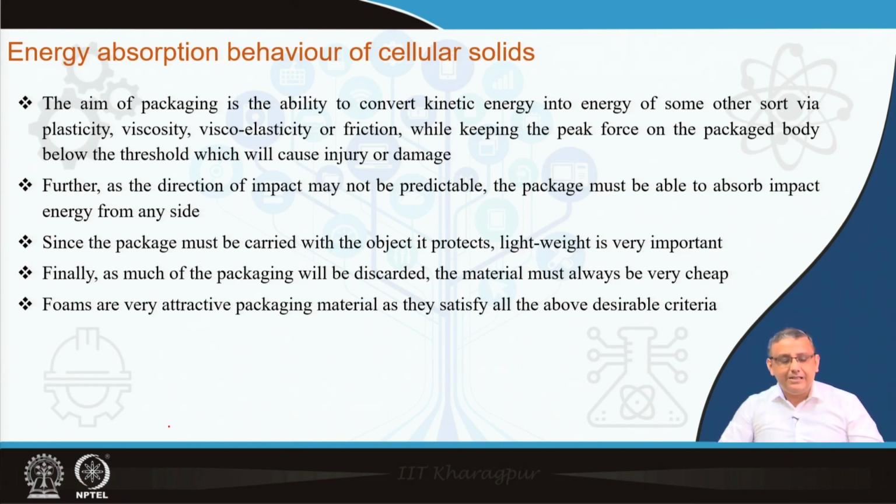Now, because of these things, as we already learned and will also see in the next few slides, the deformation behavior of the foams is very important. We learnt about them in detail in the last few lectures, and we will also go through some details in this lecture. But what are the most important properties for foams if they are to be used for energy absorption applications? One very important point is that the crash can come from any direction, which means the package must be able to absorb the impact from any side. That means the isotropy of the foams is very important in this application.